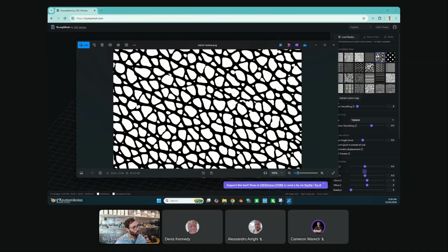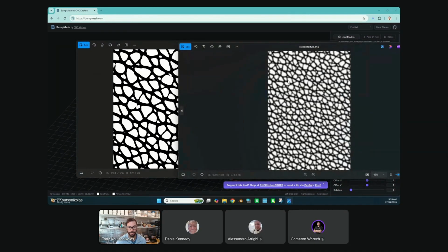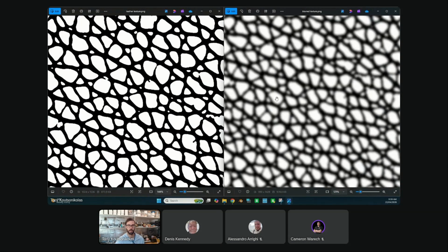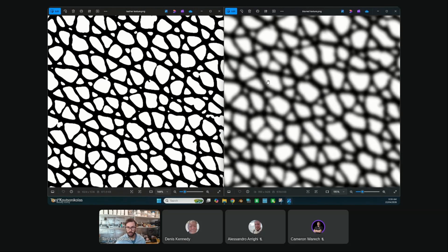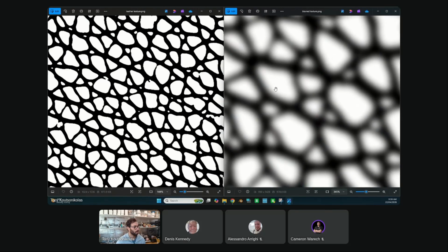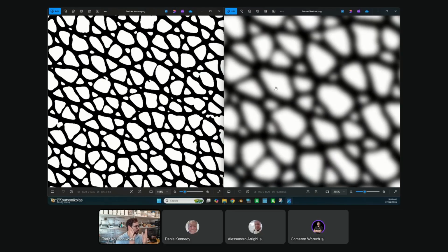Now, if I have gray here, let me open up a blurred texture. So I'll put this next to it. You guys see that? I'll chuck this one there. So I've got two textures now. One's blurred, one's just black and white. Now, if I zoom into the blurred one, it goes from solid black to solid white with a transition. Say where it's 50% between, so 50% gray, then that is where we're going to have half the amplitude applied. So in this respect, I'm creating a texture smoothing effect, okay?